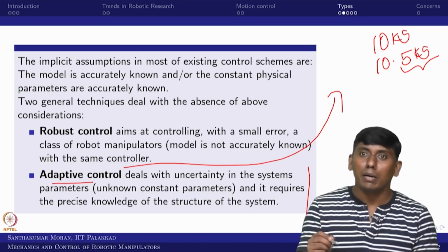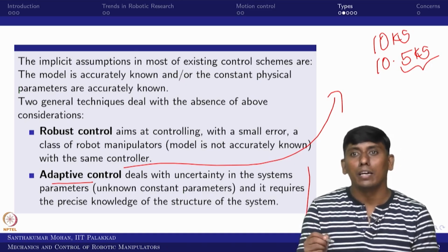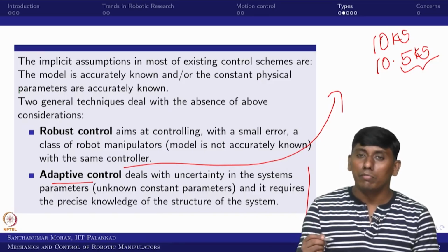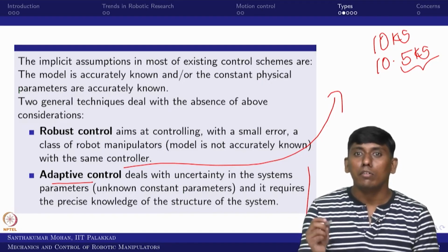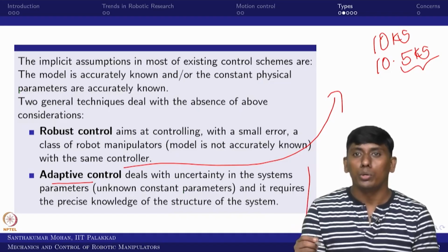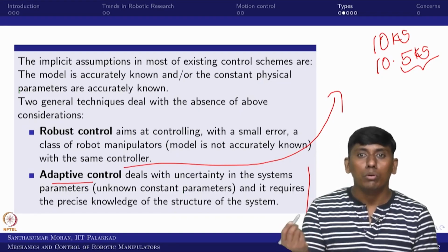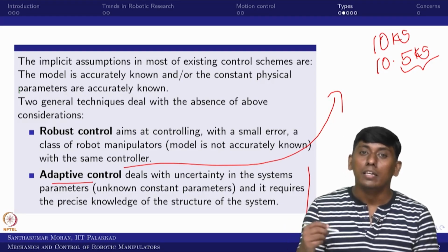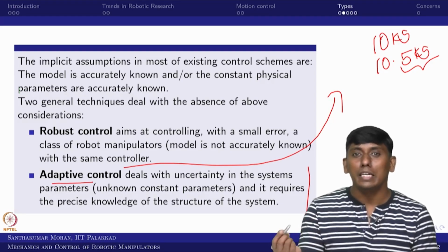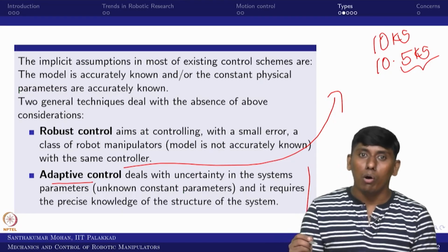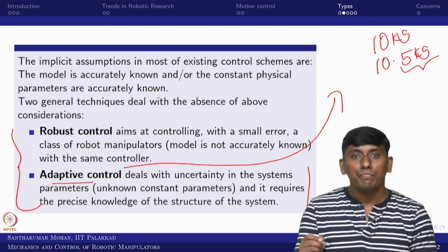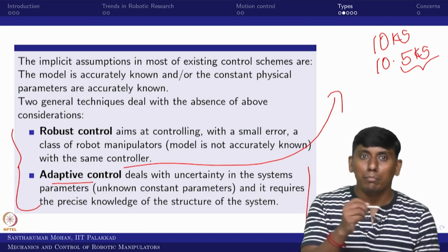This regressor matrix usually would be rectangular, so you have to take a rectangular inverse, and in most cases the regressor matrix inverse is more prone to being singular. In that sense the control input could go to probably infinity. This can happen. That's why non-regressor matrix, or inverse-free, adaptive control has come up in modern days. These are the two types of control apart from motion based and